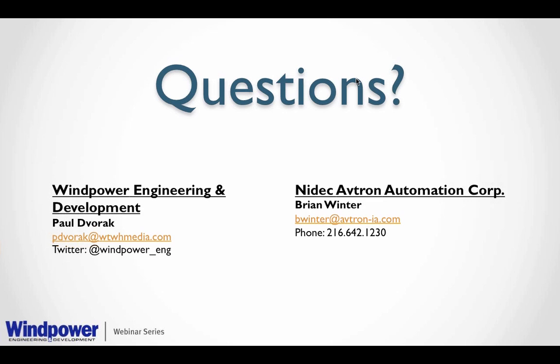He says, what drives the specification of resolution for wind turbine mounted encoders? Insanity. Actually tradition. Various vendors with their control systems put resolutions of encoders on their feedback systems. But honestly, for blade pitch systems, almost everybody has a lot more counts than they can ever possibly use, because most people are actually measuring counts or position behind the motor. The motor might have a 27-to-1 gearbox between the motor and the movement of the blade, so for every revolution of the motor, you only see a tiny amount of degrees of change in the actual blade. So a lot of manufacturers honestly have a lot more resolution than they need.